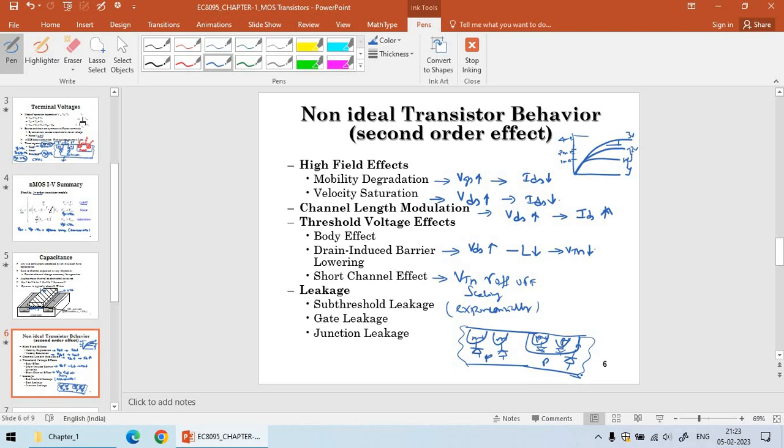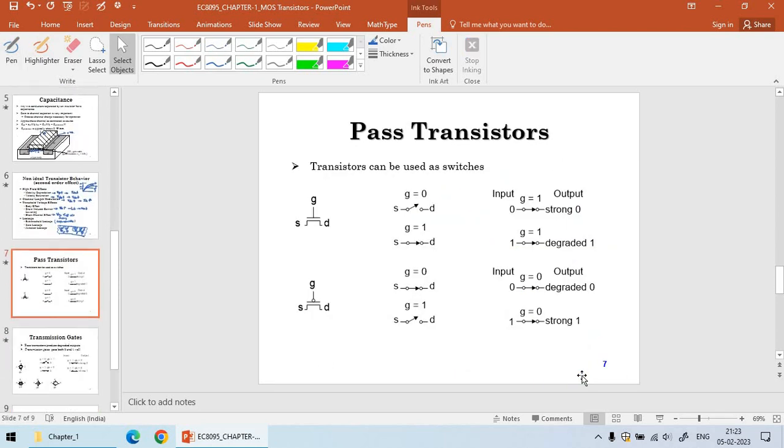So this is to be considered, because for two transistors itself we are getting a leakage current from 5 reverse biased diodes. So if you take millions of transistors, the power consumption is going to increase, because power is nothing but voltage into current. When this leakage current is more, then the power consumption of the IC is going to be enormous. So we have to control this.